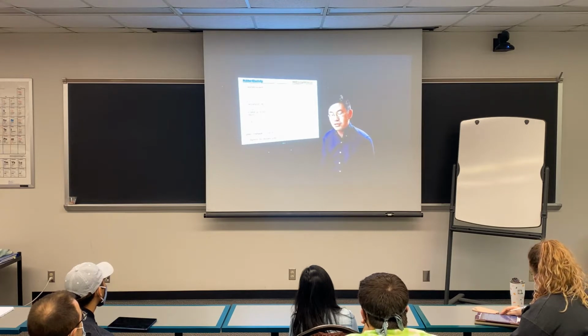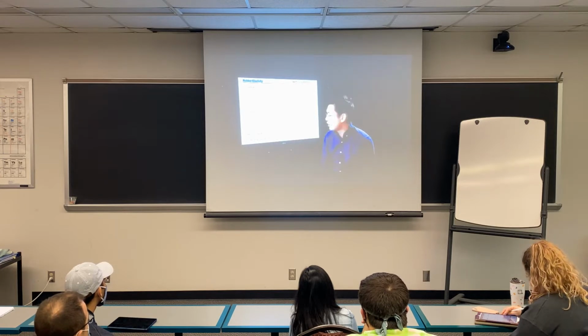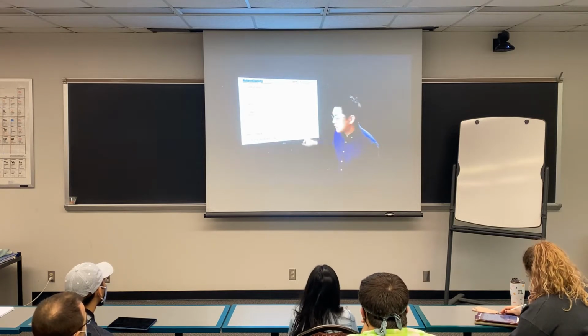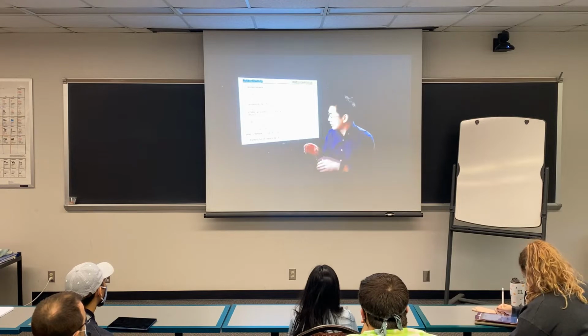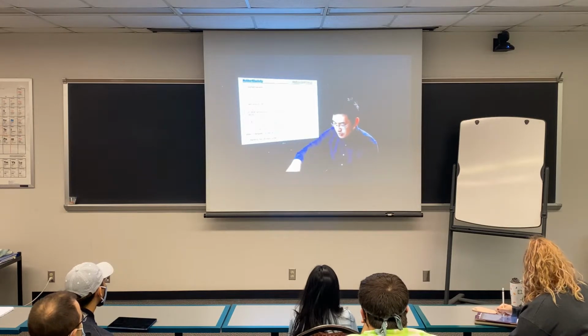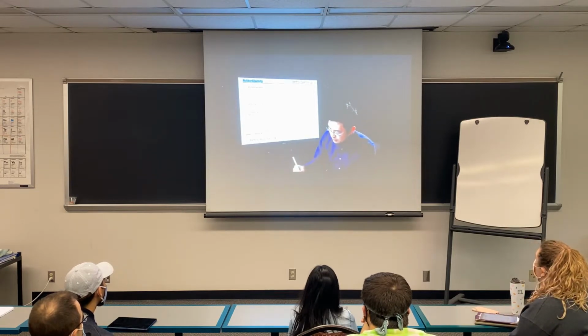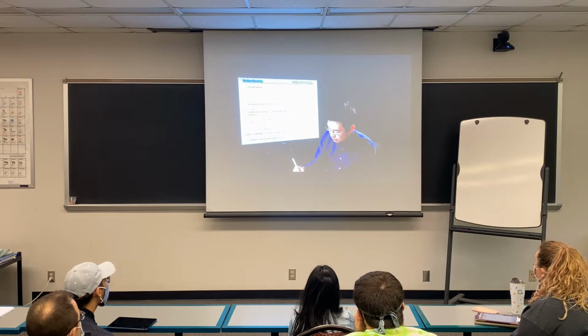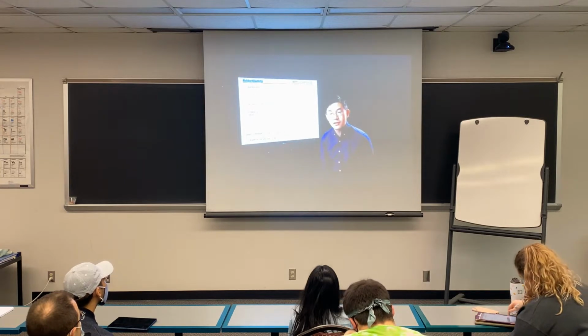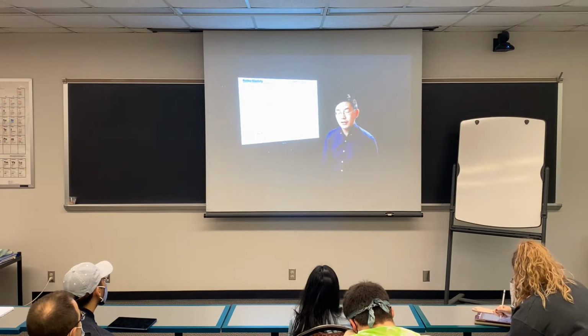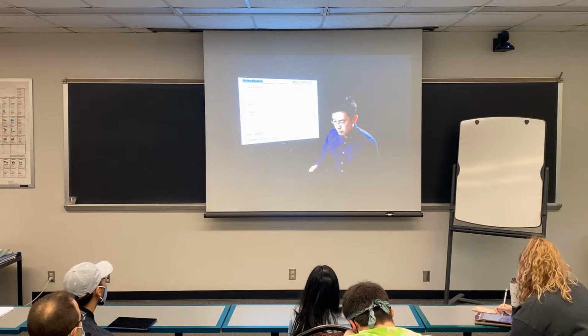Okay? There are also people who started a term for the network. They imagine whether it would behave like a chain fluctuating around its ideal mean position. In other words, let me get my pen. In other words, phantom network basically says you are no longer fixed at here. This crosslink point could fluctuate within this sphere. And within this sphere it allows you to slightly modify the crosslink density. So that's the difference between the two.